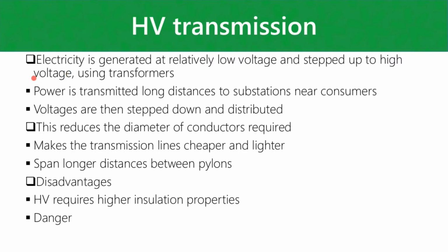Right. So if we take a look at high voltage transmission now, at your power station, you guys will actually be surprised at how low the voltage actually is at some of these power stations. So we usually generate our electricity at a low voltage, and then at a substation part of the power station, we step up the voltage for transmission. This is usually done to keep the amount of current flow low on the transmission network. So if you step up the voltage, the current comes down.